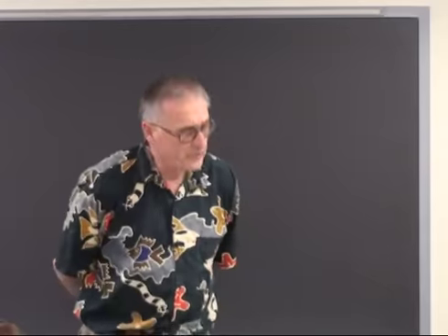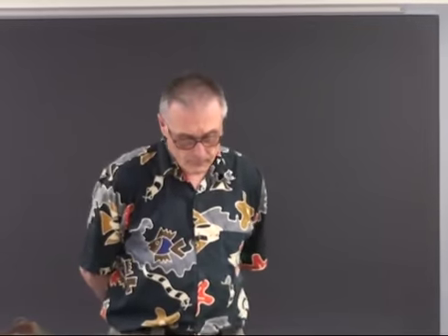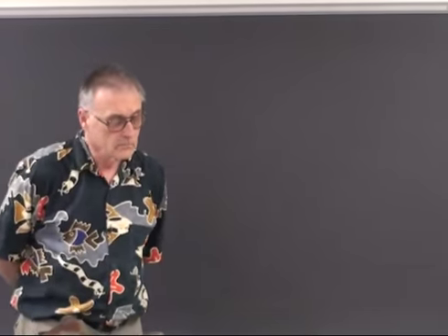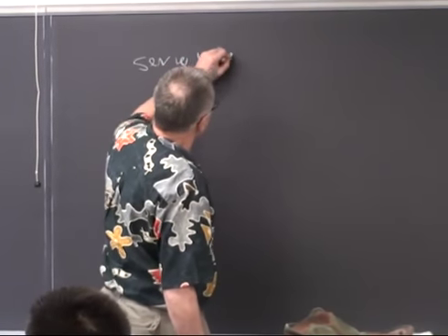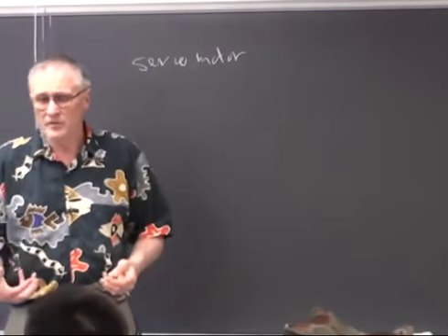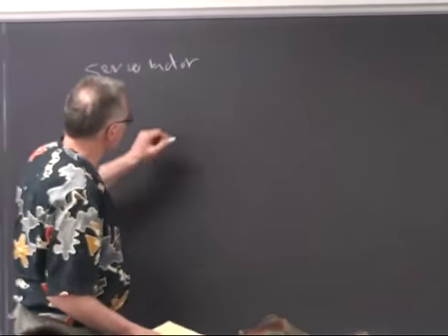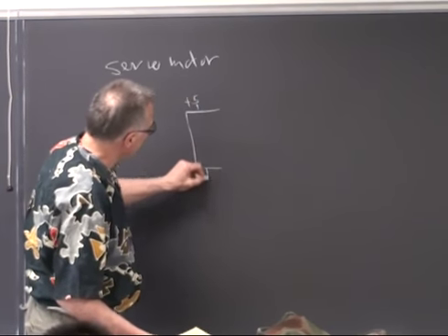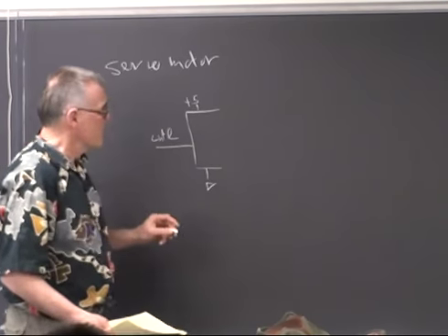But the one we've used so far is the so-called DC motor, which is you put a voltage on it, it spins. But there are other systems that are quite useful. One is a servo motor. And that's a DC motor that has internal feedback in it so that it is more controllable. Servo motors have 3 leads. You would have a +5, a ground, and a control lead.